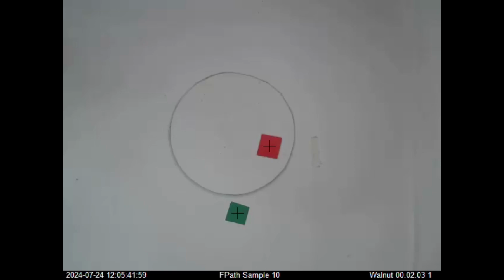So the Walnut software on the Windows 10 PC can do image recognition on the squares, and it basically figures out the coordinates of the two colored squares and the colors they are. The center of the rotating platform is not known. Once the coordinates are figured out, they are sent over to a BeagleBone Black microcontroller running some software called the Walnut Client software. This software has a kind of PID-like algorithm in it which controls the motion and can generate the speed and direction commands to control a geared stepper motor which is driving the platform.